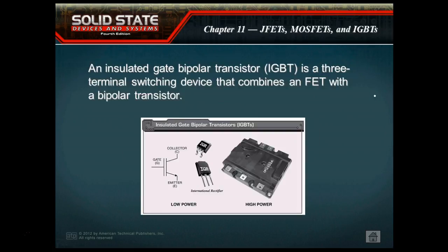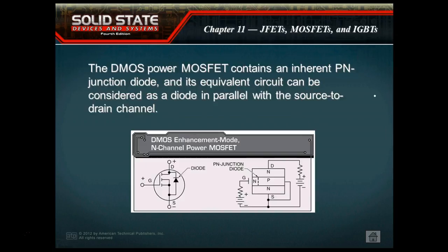Okay, what they've done is they've combined a MOS input because it switches easy. We exceed the threshold voltage. It's on the ease of switching and the speed of switching because it doesn't saturate, along with the power handling capabilities of a bipolar junction transistor.